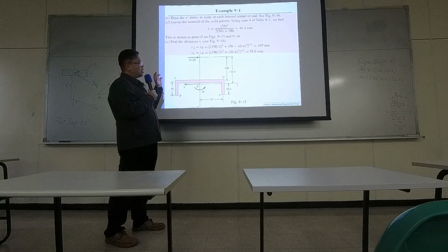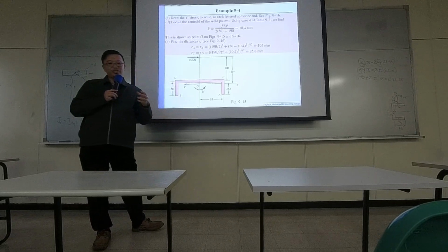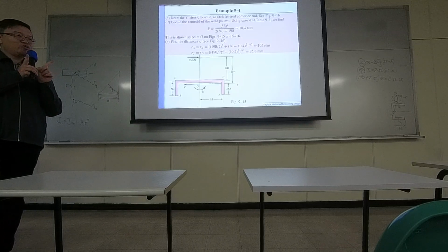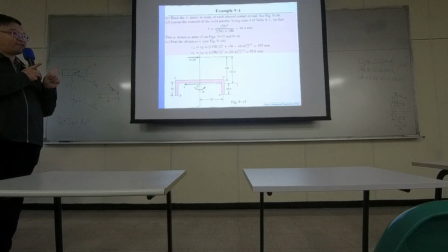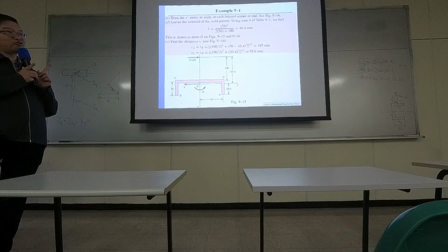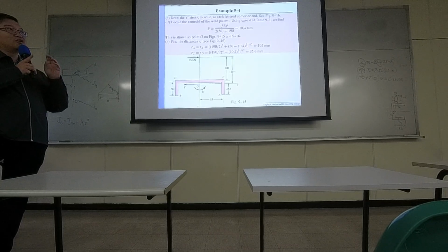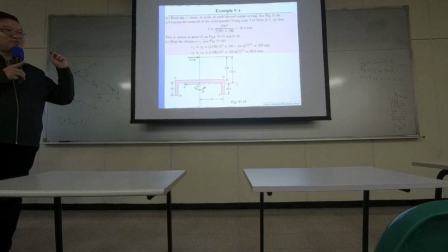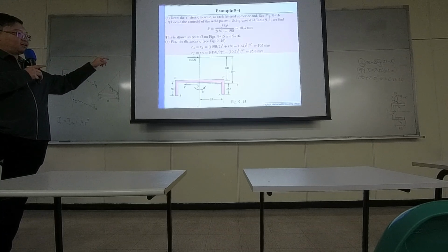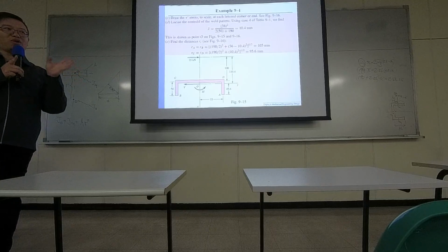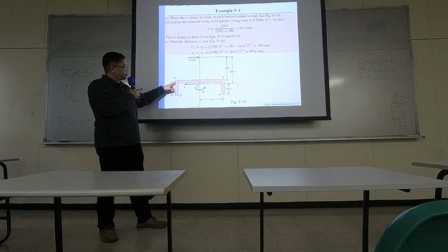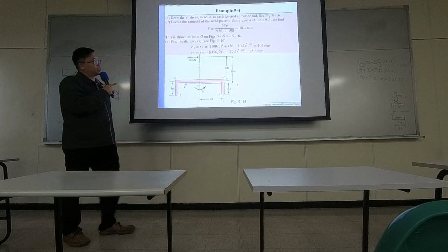Because there's normal shear and this rotational shear, and they will have different angles. So in order to figure out the overall maximum shearing, combining the normal one and the rotational one, you really need to compute all four situations.